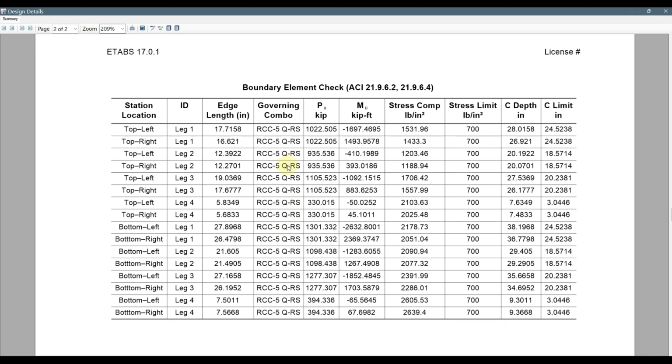because the response spectrum has been scaled to 100% of the static base shear in our case. So my practice is that for designing the vertical elements, I always consider 100% scaling of the static base shear, if the response spectrum base shear is less than that. In our code, which is BNBC 2020, it actually allows 85% scaling.